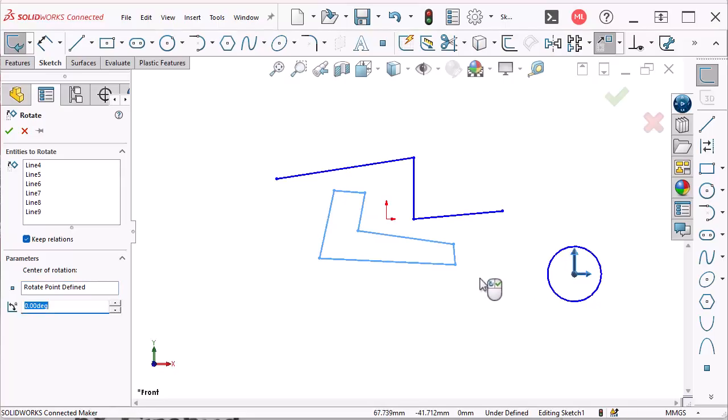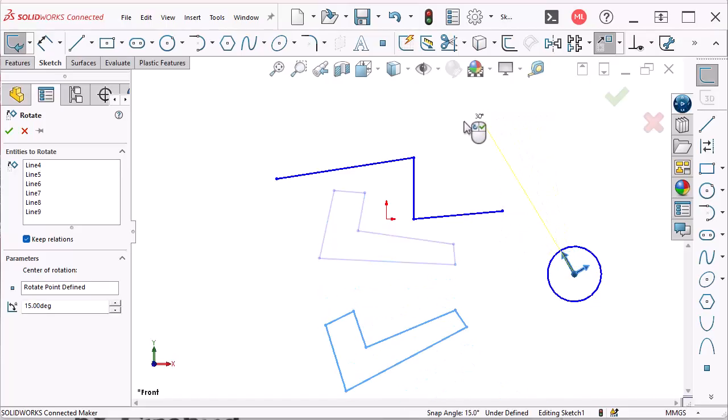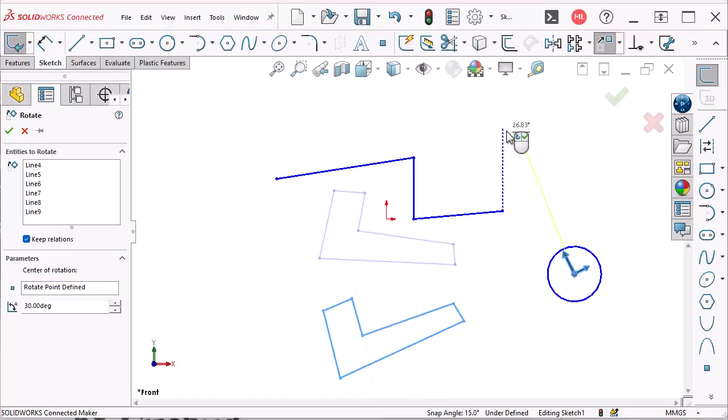And notice now that my cursor has the left mouse button, which is a curly arrow. My right mouse button is a green check mark. So the curly arrow is telling me that dragging the left mouse button is going to give me my rotation. And so I'll do that. And this allows me to rotate that selection wherever I want to put it. I could also key in a value in the property manager. Notice the temporary origin shows up and turns, but the sketch origin, the part origin, do not move.